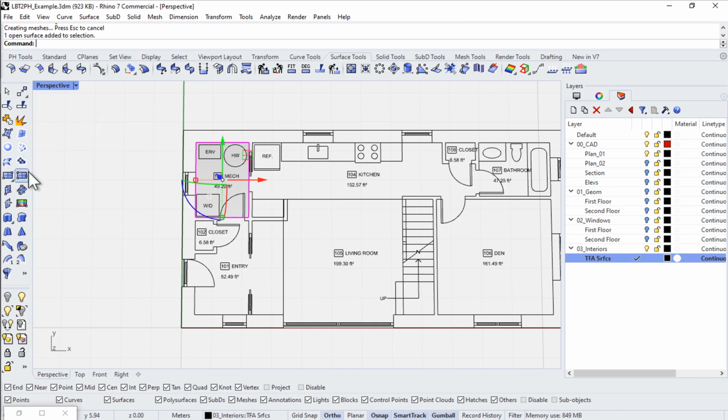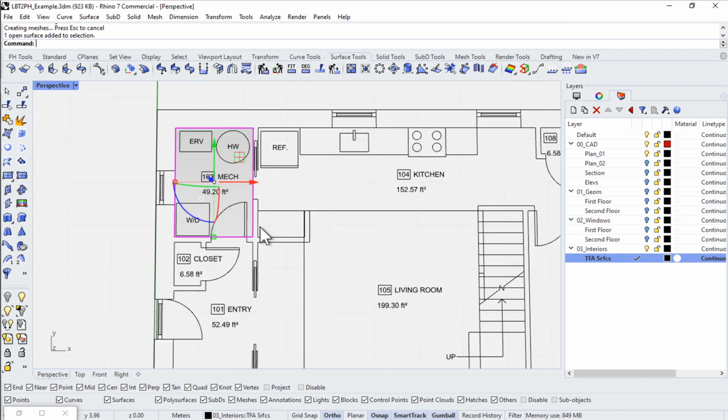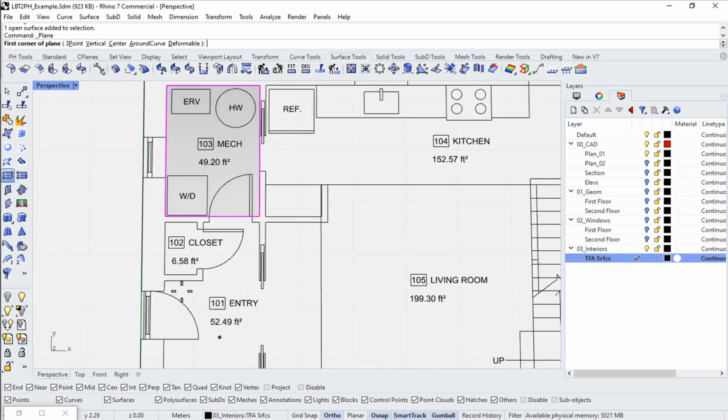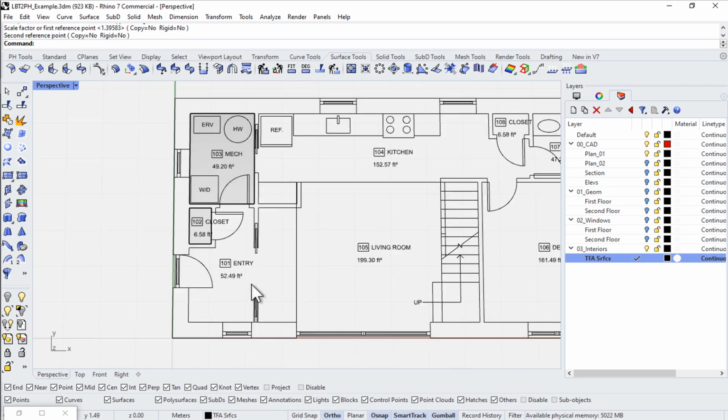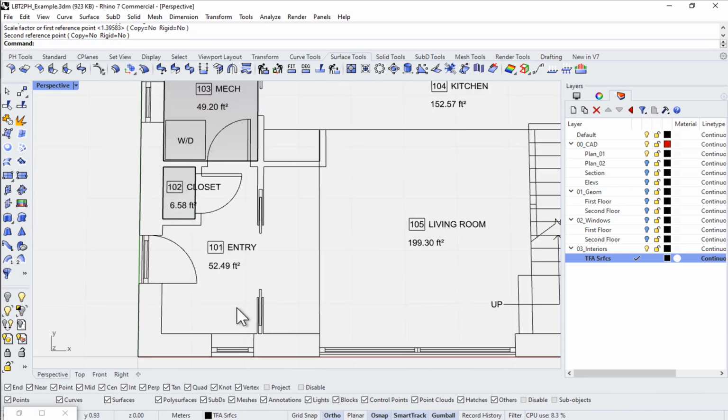And as we talked about before, normally I would not recommend snapping directly to the CAD plan. Normally I would say you should do something like this, and then use your scale tool to reconfigure that, make sure that it's an actual rectangle. In this case, I've gone through everything and the geometry is very clean, so we can safely snap to all of our vertices here without too much worry.